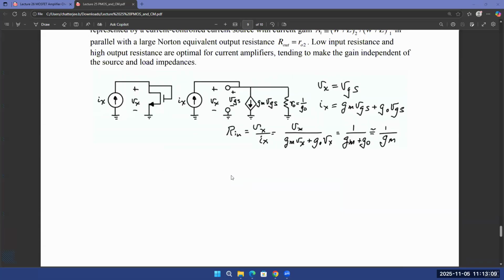Now, how do we analyze this? Of course, we draw the AC small signal model. Let's just first concentrate on the left side transistor. Okay, the left side branch, where you have a current source. And this is an AC current source right now. So you know that when you do AC analysis, you kind of neglect the DC, right? Because DC and AC, you can think of it as two different analyses which are superimposed on top of each other. So when you're doing AC analysis, you don't need to consider the DC quantities at all. That's why we connect our VDD to ground, because our VDD is an AC ground. That's why you get rid of any kind of DC voltages or DC currents in the circuit.